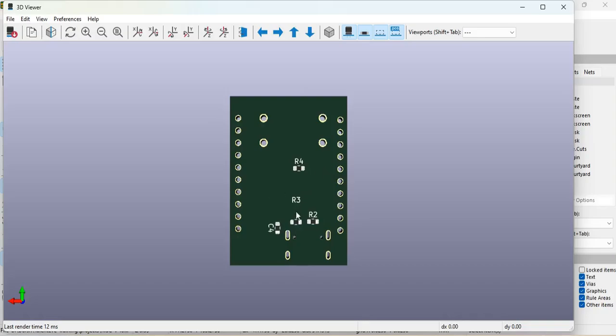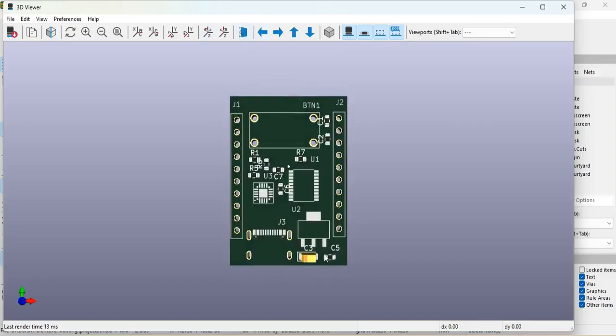And one thing you see here, R3 is far away from the actual component. Okay, this is one important observation. And we have to ensure that C4, whatever is there, as it cannot be accommodated at this juncture, is placed on the bottom. So ensure that it is very close to the respective pin. So these are the observations which can be made using the 3D view, and a very helpful view, right? For beginners in PCB layout, this is very important.